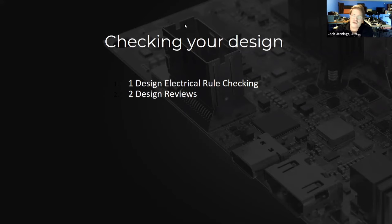So it's better to try to create your designs based on more traditional standard parts. Like I said, in some cases, you have to use something that's unique. If you have to, you have to. But understand that's a risk and inform purchasing, so that you get any end of life or obsolescence notifications. You need to consider what you need to purchase to cover your expected lifespan for the board, or conversely, how much you should buy in order to cover the amount of time it's going to take to redesign the board. And that is a guess, but I've seen that in a couple of places.